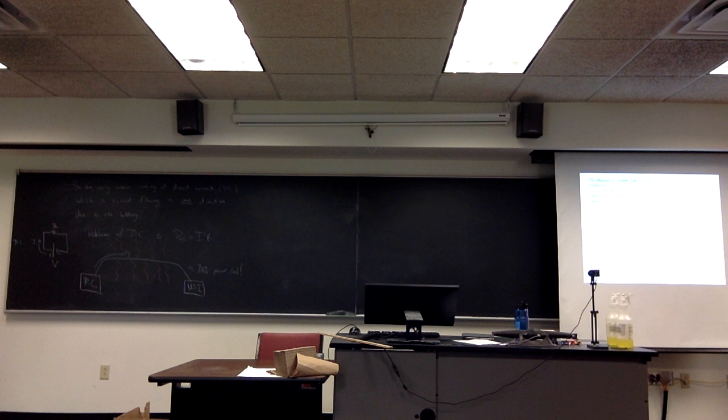So basically, the power loss is the same as the power supply. The electric company is supplying you a certain amount of power. So what you want to do is take that power and multiply by the amount of time in hours. You've got 24 hours per day, times 7 days a week, times 20 or 30 days. Multiply those together, that gives you a certain amount of energy. And you're going to take that and multiply by 15 cents.